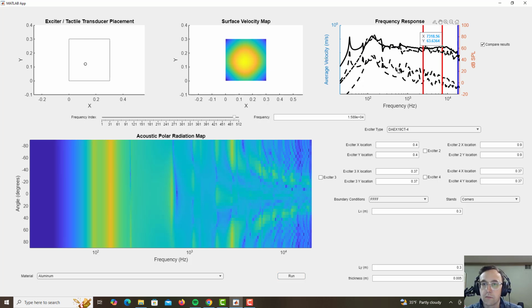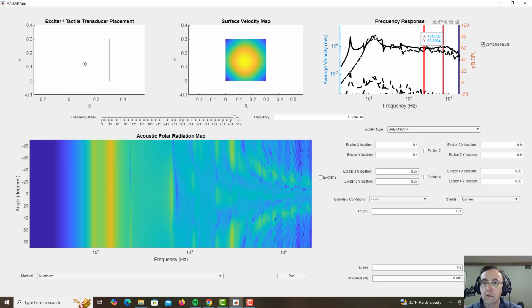So here, again, let's move some of this stuff out of the way. So it doesn't really start bending until 145 hertz-ish. Let's see what's going on. Yeah, that's this. You know, so actually that's not horrible. I thought it was going to be a lot worse. But the coincidence frequency is really low. Yeah, you can see, here's the coincidence frequency. This is when the radiation starts beaming parallel to the edges and then starts to move inwards. So, not great.